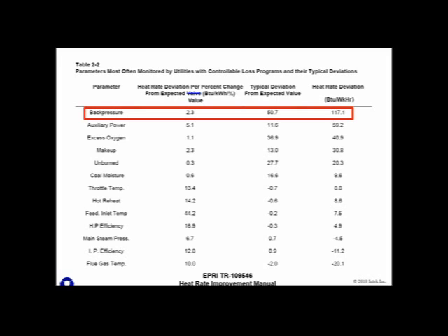For example, several years ago, a customer of ours within Southern Company had an expansion joint failure located between the feed water pump turbine exhaust and the condenser. So they have a turbine running a pump that's pumping the feed water into the boiler, and that's steam driven, obviously. That steam exhausts into the condenser, and there's an expansion joint there. That expansion joint failed. It allowed a bunch of air and leakage to come in at that joint. That failure let in about 100 SCFM into the condenser, which is a lot.